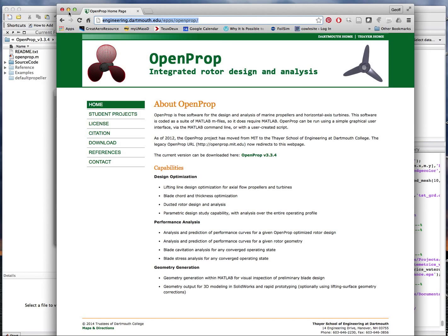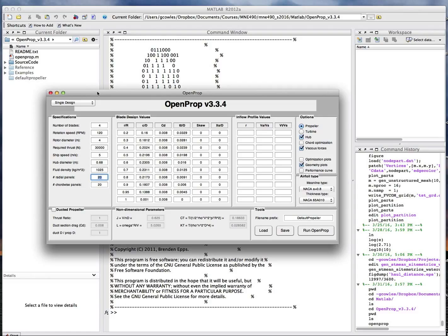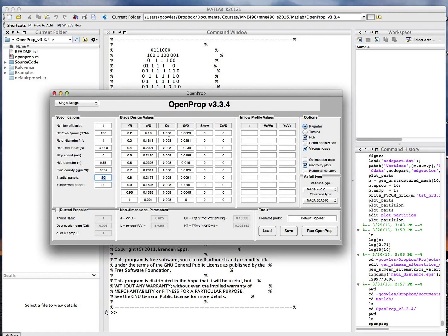As I said, it's an inviscid program, so you have some drag on the blades, which leads to part of the requirement of torque or horsepower due to the induced drag, and you also have, of course, viscous drag, which is approximated in there.